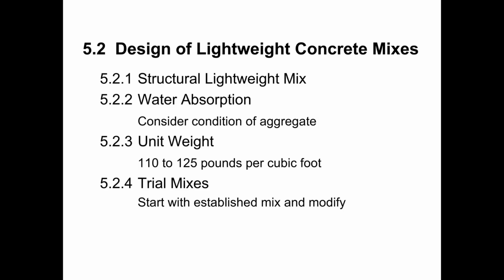It's unlikely that they will be able to provide you with a mix design that is exactly what you need. More than likely, you're going to need to tweak that mix design to some extent, either with regard to the cement content to dial in the strength so that it's not overperforming or underperforming on strength, or maybe you need to make some other adjustments to modify the workability of the mix. Either way, trial batching is the tool that should be used in that process.